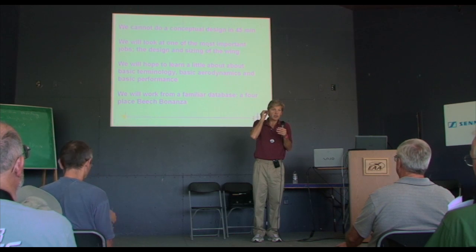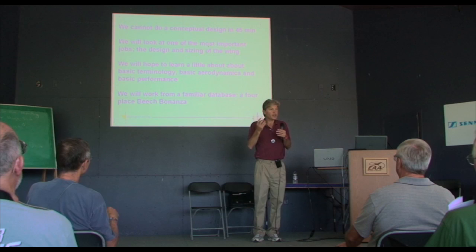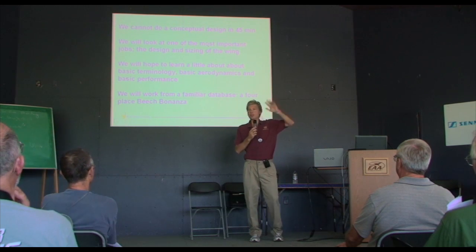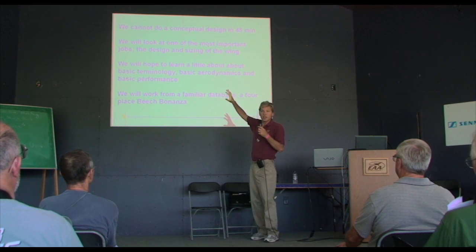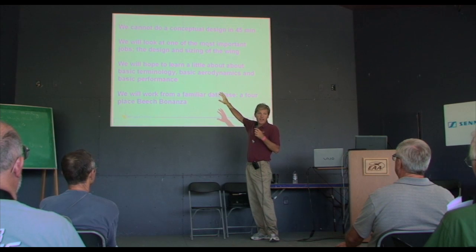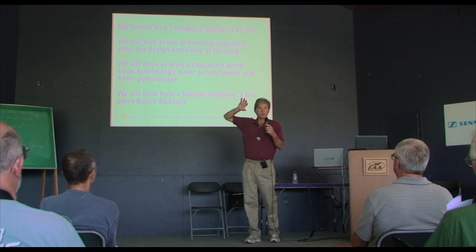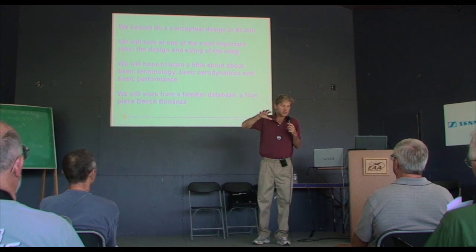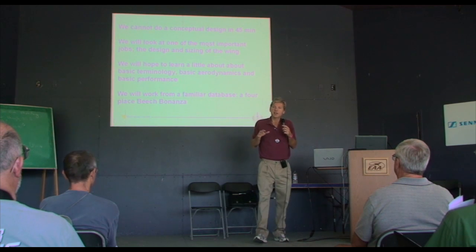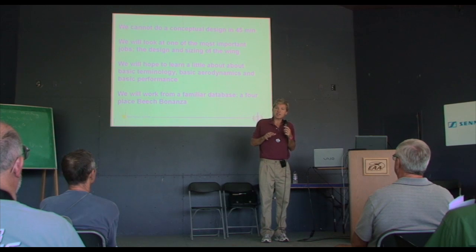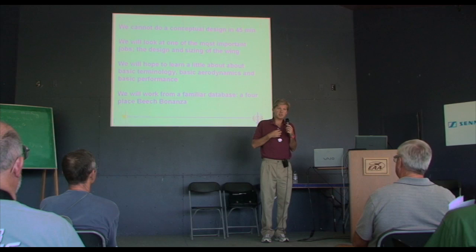And what we're going to do is look at designing a new wing. Also the power loading is going to stay constant. Okay, so we're just going to set the power loading as it is. We're going to set the useful loads as it is, set the takeoff performance as it is, and we're going to look at improving the wing design to see what we can do for the overall performance of the airplane.